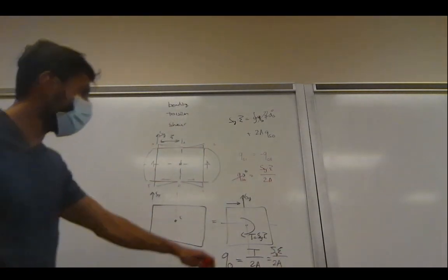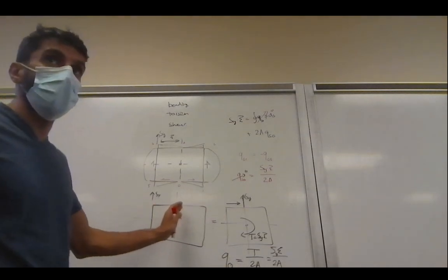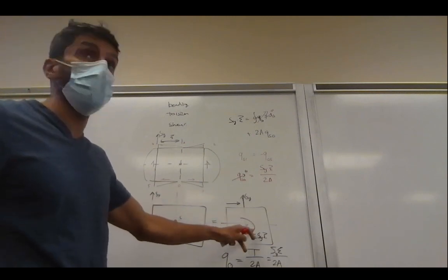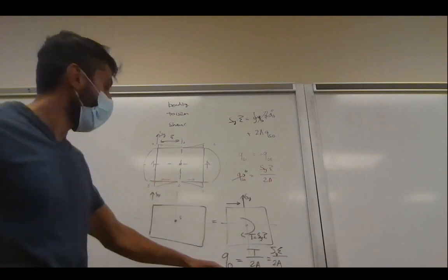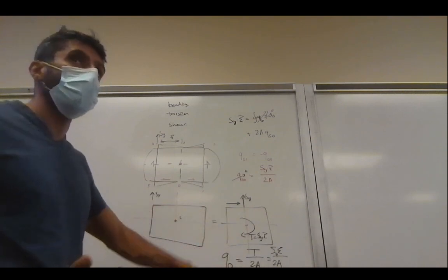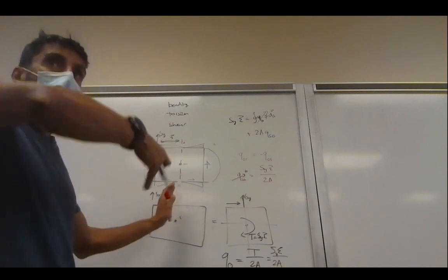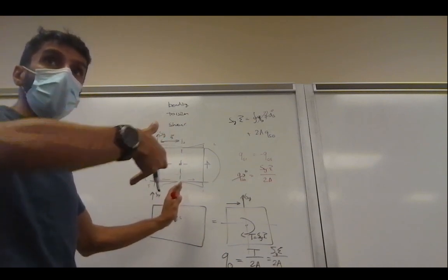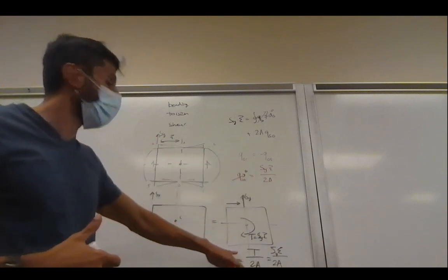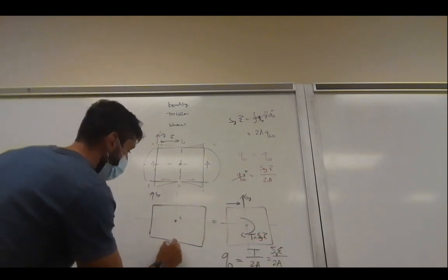So what we basically did is we moved the shear force to the shear center, and we made our lives a bit easier, but we added a torque to it, which creates a constant shear flow. And in this case, the solution will be exactly the same. So this is a very simple problem, but for more complex problems, sometimes moving the shear force and adding a torque to it simplifies your life, because sometimes this moment equivalence study can be more complex than this quick trick you do here. Because if you do it correctly and if you make the cut in the right location,